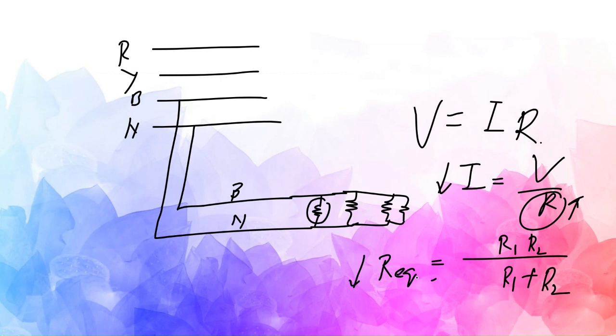All right, I think you have understood this, right? If it had been a series circuit, then this reasoning would have been okay: you are increasing load, decreasing current. But that is not the case here. Here it is an equivalent circuit of a parallel circuit. The equivalent resistance of a parallel circuit will go down as you keep on increasing these loads.